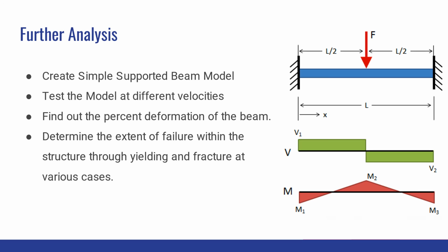We also did some additional analysis within LS-DYNA. We created a simple supported beam model to test the specimen at different velocities. This allowed us to determine the percent deformation of the beam at different rates. Using this simulation, we can determine the extent of failure through the yield and fracture of each case.